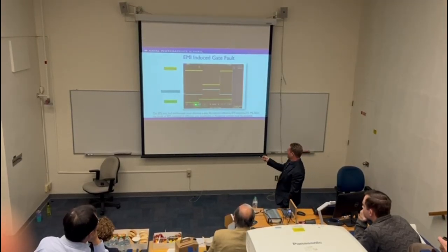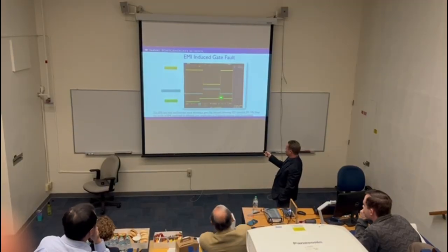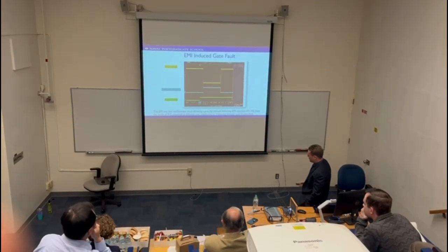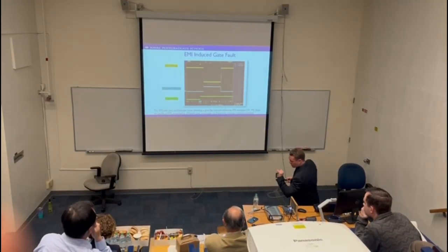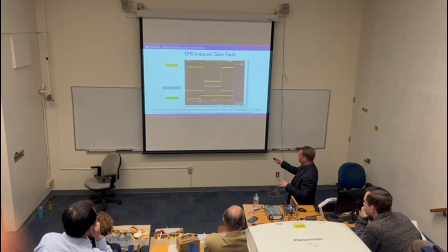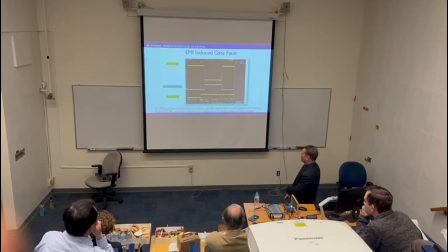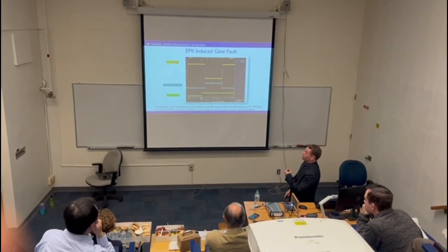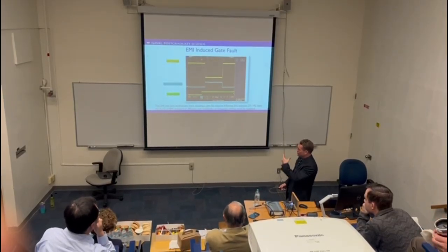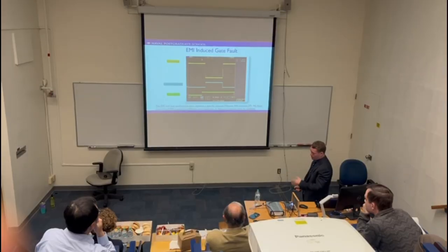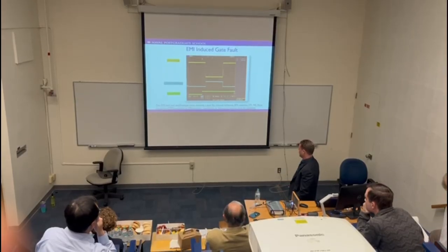Okay, so you can see here on the bottom, this is the actual trigger signal. That's actually triggered by the injection of that modulated trapezoid. You can see 200 microseconds later, all of a sudden my gate drive port sends out an optical fault. So it was very clearly attributed to the injection that the master's students injected into that.